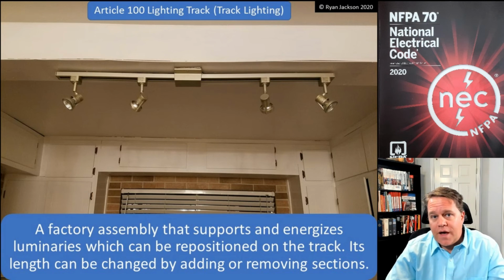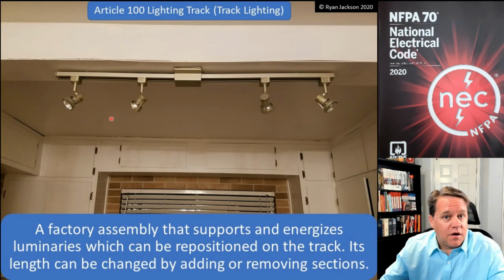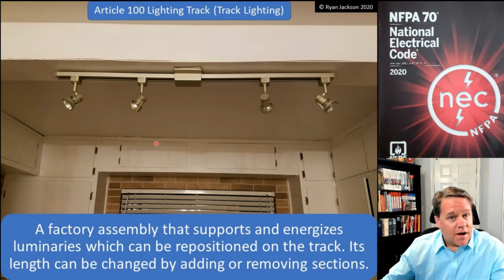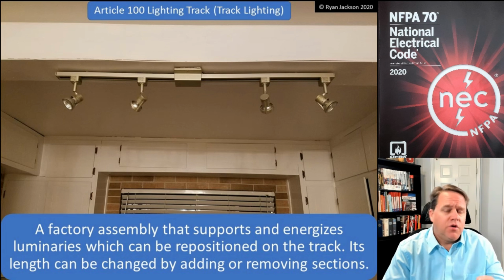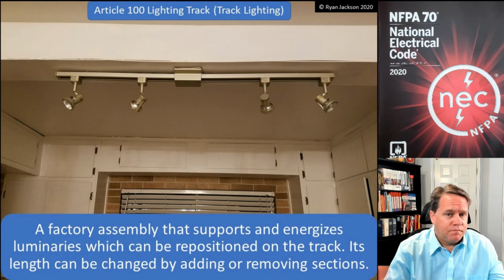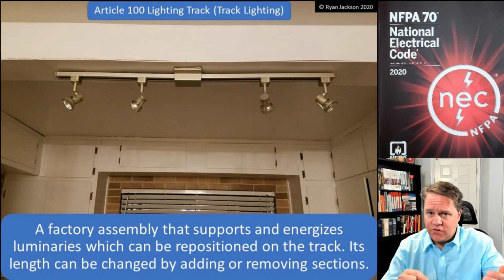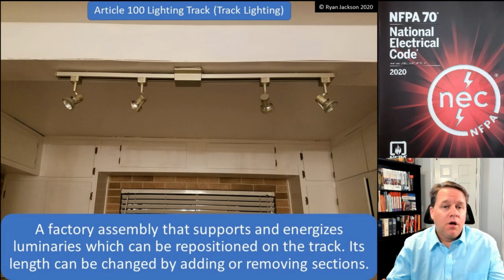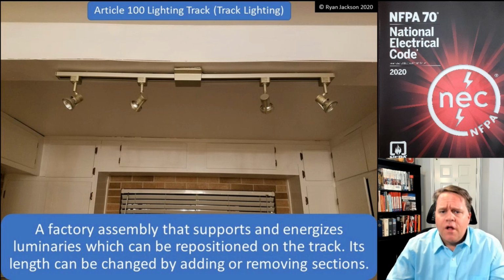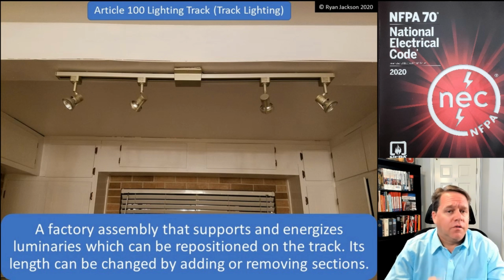The only limitation that you have on a circuit for lighting track is that the number of actual installed luminaires must not exceed the rating of the track. And the rating of the track can't be less than the rating of the branch circuit. So if you have a 20 amp branch circuit, you can't put more than 20 amps worth of luminaire heads on it. Makes sense. You also can't put a 15 amp rated track on a 20 amp branch circuit. If you did, and you put 20 amps worth of heads on it, well then the track could fail before the circuit breaker or fuse would open. So those are the code requirements for track lighting. There's really not too many other than the calculation and the rating of the track.